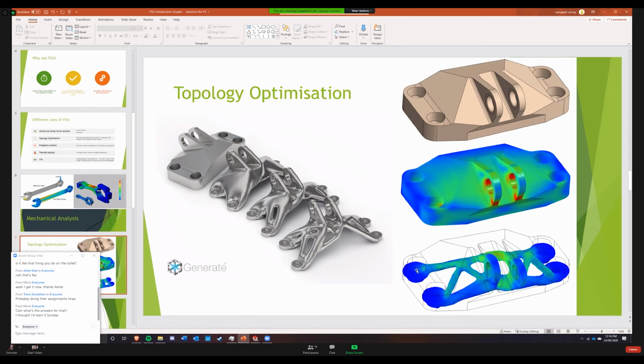And then you can see this really strange organic structure that's left over. And this is what the solvers actually come up with to say, yes, this will do everything you want it to. We've removed X amount of weight. And then you can see on the left-hand side, these are the steps that they've taken to remove weight. Now, you could actually manufacture this through 3D printing. You couldn't use traditional machining methods. So you can start getting some really, really cool stuff.